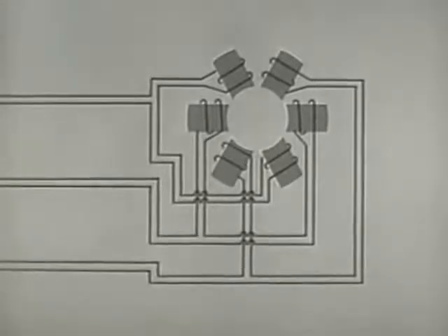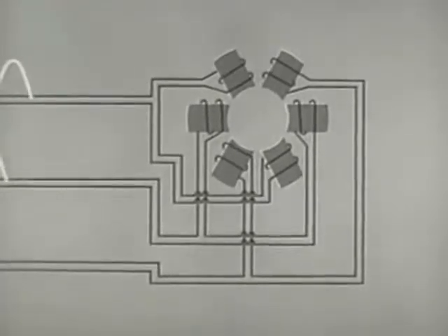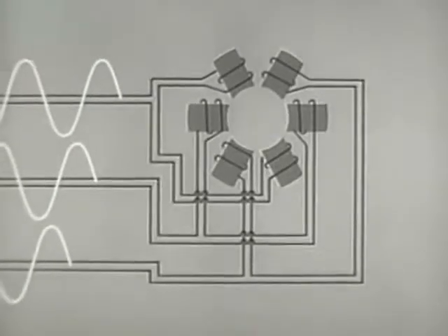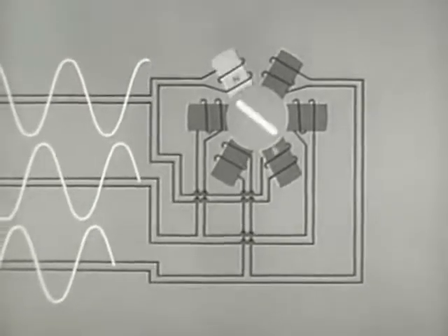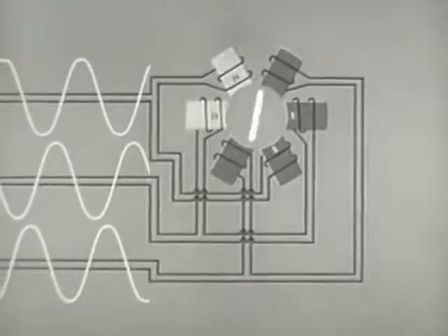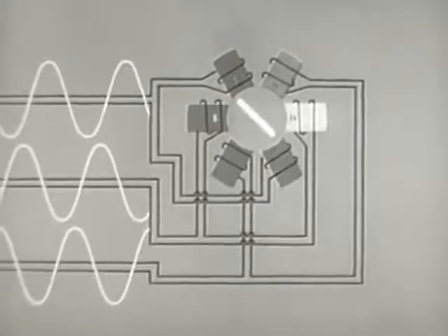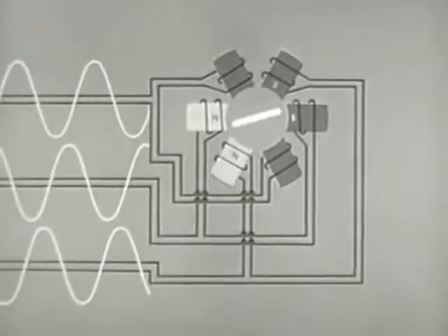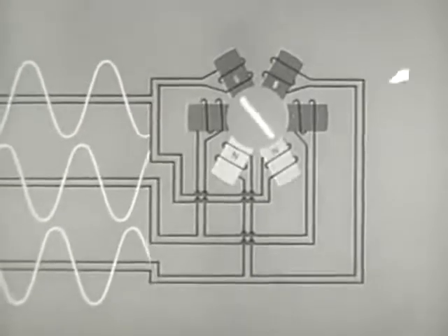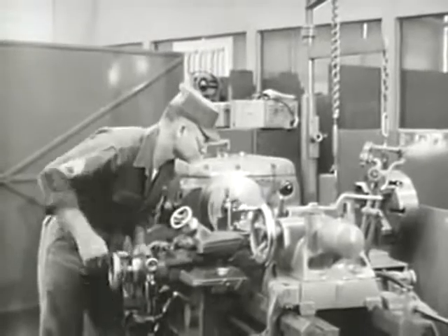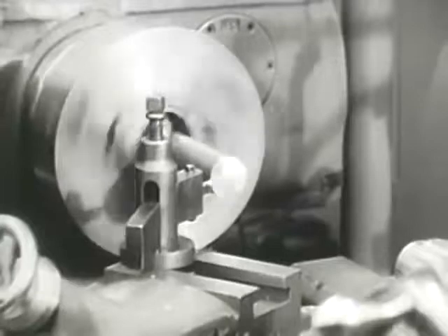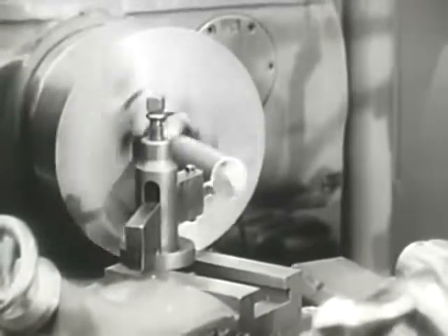These three pairs of conductors, one pair for each AC phase, supply the field. Because of the time difference in the three phases, the poles will be energized in successive order, thus rotating the field electrically. Since the rotating field is cutting the rotor, it will rotate in the same direction as the rotating field, but at a slightly slower speed. Three-phase motors have special value in situations where it is important to maintain constant speeds under changing loads.